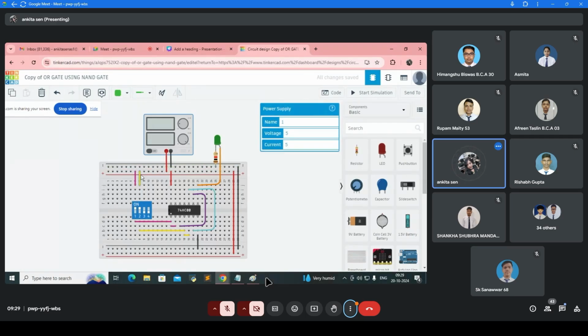Here you need to give the power supply. Did you understand what I have to tell you? First of all, you need to connect this DIP switch here only. Means you cannot connect it here, here, or here. You need to connect it in this portion, like this IC only. Correct. Next, where the on letter is indicated, from here only you need to connect the plus sign indicated line, correct, this way. Now from here you need to get the output, or make the connection to this IC.